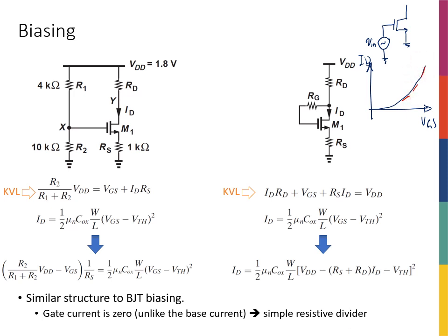That means that in addition to this signal source, I need to have some sort of a DC source on top of it, and I'm going to call that V bias, right? If the threshold of this transistor is 0.5, this should be somewhere a little bit more than 0.5, so that the transistor is on, and then I put my signal on top of the DC voltage at the gate, and then I'm hoping that I'm going to get a good gain.